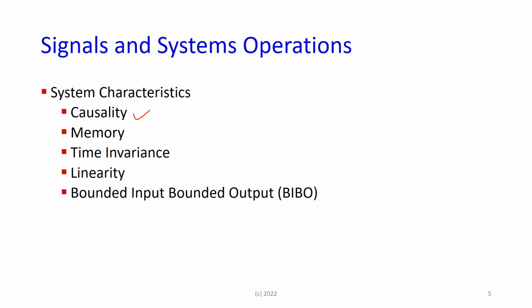If you start to look at the power supply, it is off for a while, but if it's a good power supply, the filter capacitor will be holding some sort of voltage value. So when you turn it on, it will give you an output voltage that is not necessarily the full output voltage. It will start at some level and then settle down.